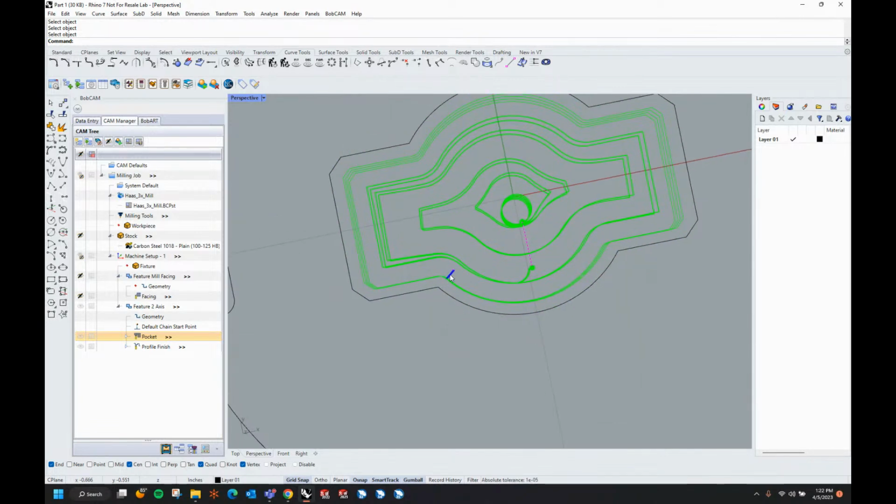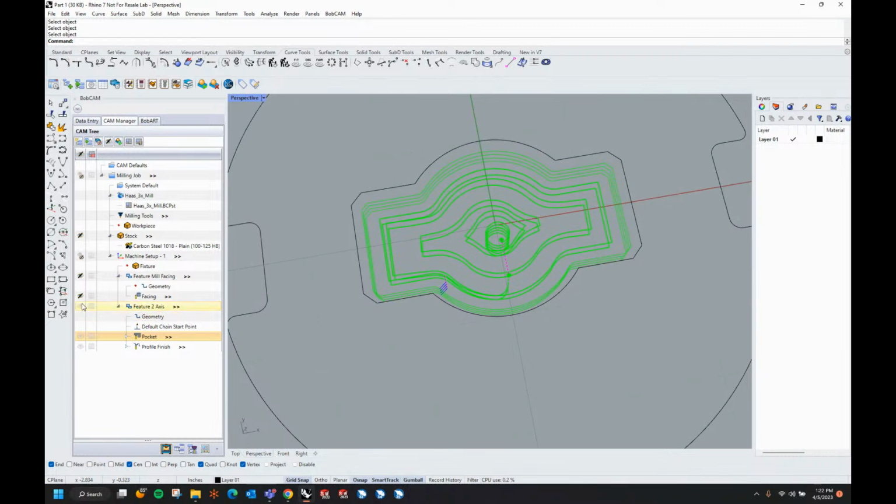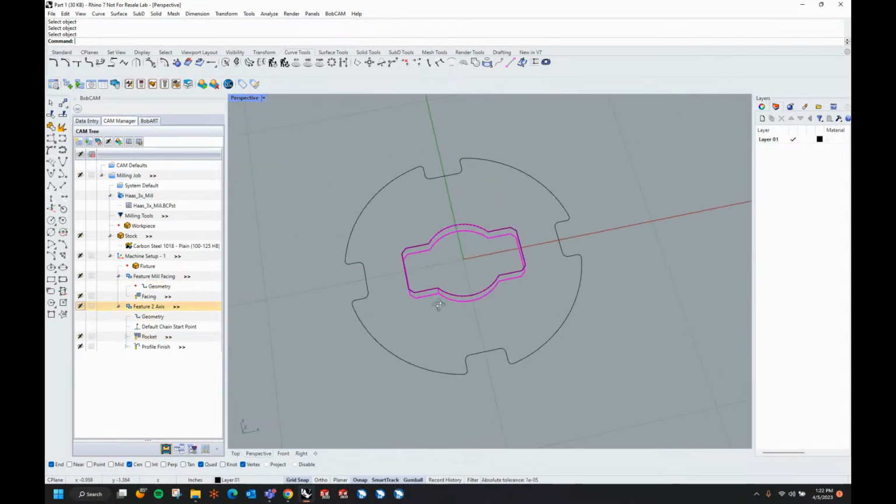And that actually changes where the lead in is kind of coming in from too. So you can see instead of it being like a V coming into it, in and out of it, it's now just one specific spot. And I can see that morph spiral coming through there. Now I'm going to go ahead and hide that path. And let's say I need to do the outside. So we have this as, let's say, 3/4 inch thickness.